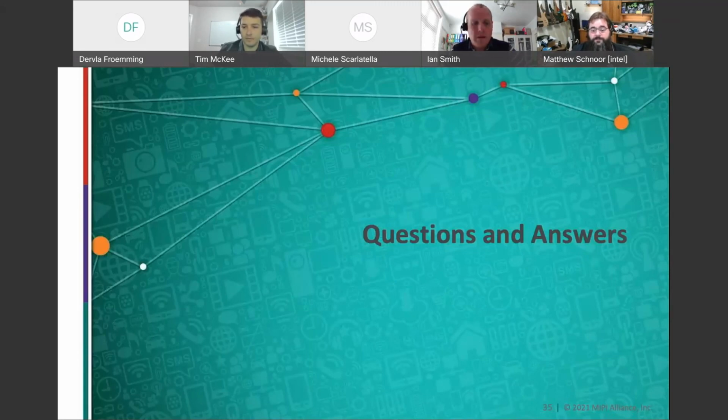And then I think probably the next, maybe it's the final question, maybe we have one more: is a 50 nanosecond glitch filter on SDA and SCL a must-have for I2C compatibility? If you want to be able to run I3C transactions at full speed and still keep compatible with I2C, you would need a spike filter.